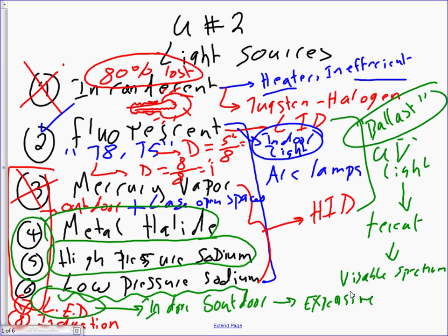Now this arc is ultraviolet. You can't see the arc. So, smarter than Chad, Ian, my friend, what they do is they treat the inside of the bulb with some phosphor material, and that chemical material converts the ultraviolet into visible light. And that's what you're looking at right here. Can I have thumbs up, Chad? That's why they call these arc lamps. So fluorescent light is an arc. Mercury, metal halide, and high pressure sodium, all of these are arcs, and they need a ballast. Incandescent lamps don't need a ballast.